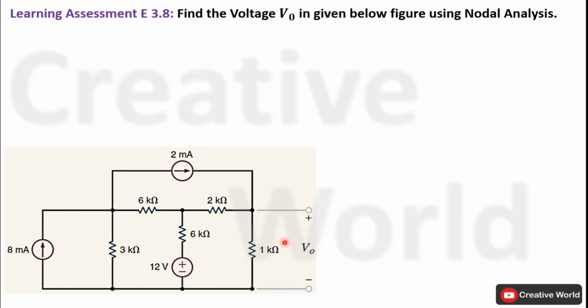We know that in order to do nodal analysis of a network, we have to follow some steps. In the first step, we have to count the total number of nodes present in that network. In this scenario, there are a total of 4 nodes present. One of them is the reference or ground node. The other 3 nodes will be utilized for the application of nodal analysis. And this network has 3 non-reference nodes, so it will have 3 node voltage equations.